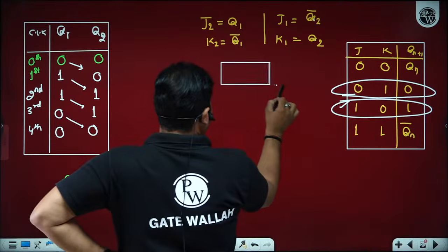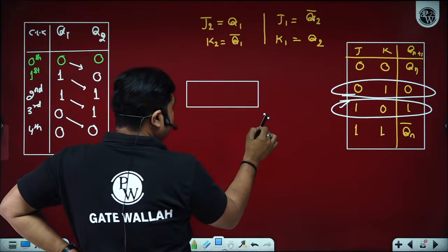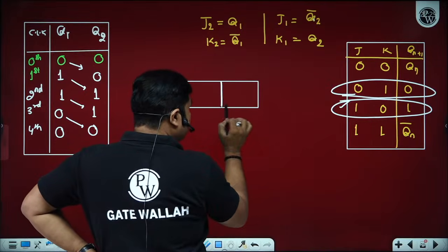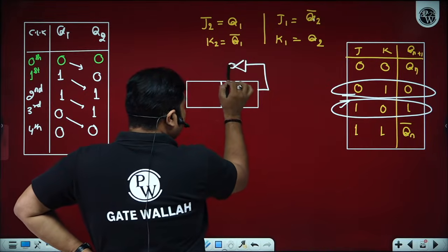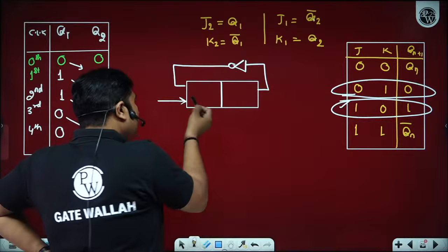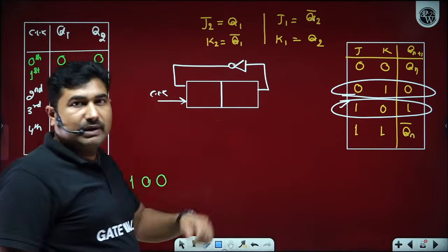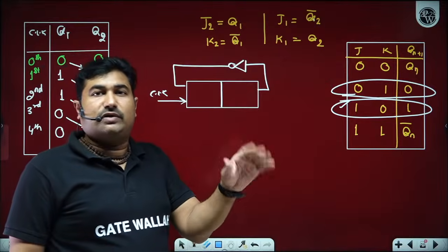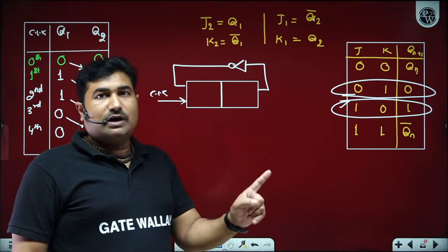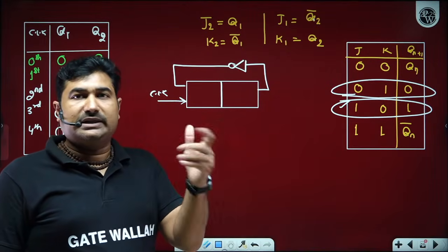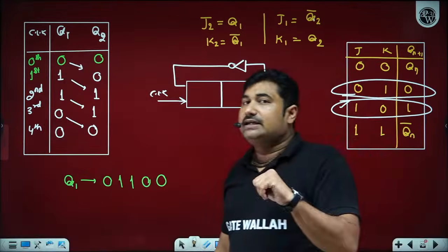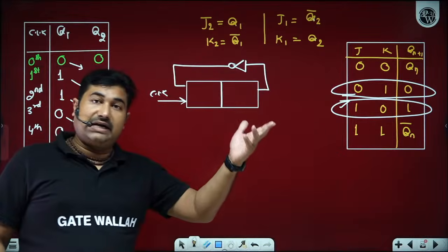Moreover, if you observe how this circuit is behaving, this circuit seems to be similar to this one. We will learn this concept in ring counters, but before going to ring counters, you will be able to solve the question by using the thumb rule. It doesn't matter how much you have read for the sequential circuit. Always remember only two things. Before applying the clock pulse, first find the input to the flip-flop, apply the clock pulse and follow the truth table. Is it okay? And the other thing you need to remember is the excitation table, where we have to design our desired sequential circuit.